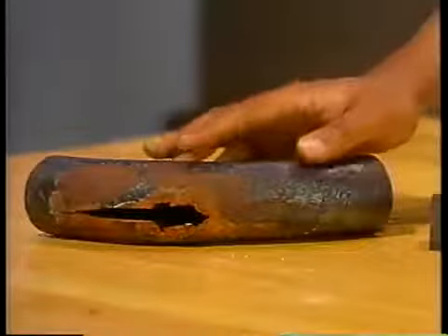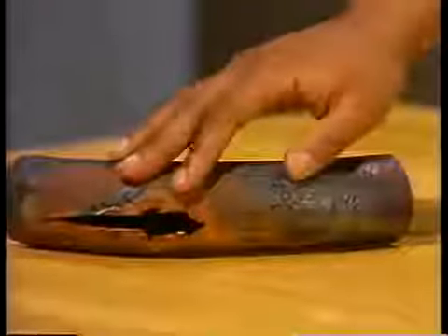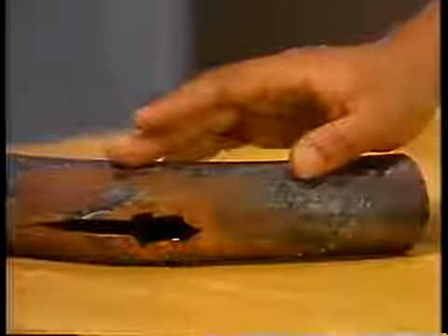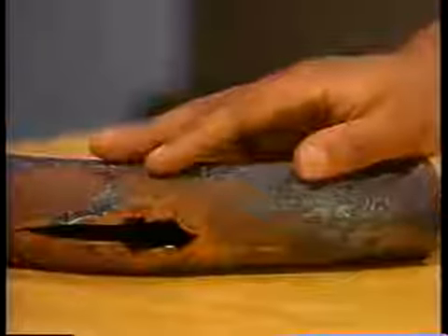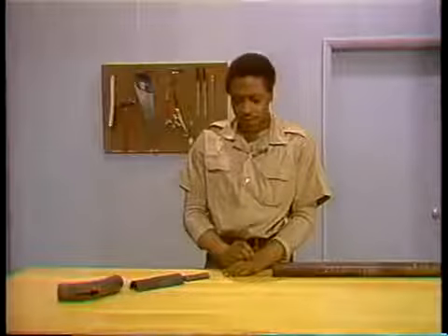Corrosion can also be a problem on the outside of the tube. Here, corrosion is the result of moisture combining with the sulfur found in ash or soot. This produces acid, which attacks the tube metal and corrodes it. Corrosive slag is still another cause of corrosion on the outside of the tube. Corrosive slag is formed by contaminants in the fuel.